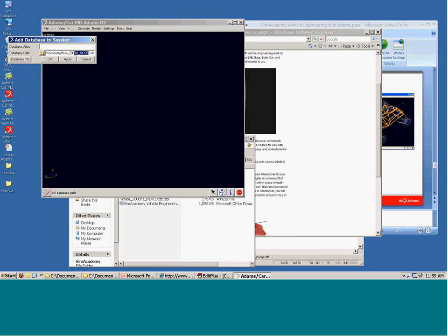Now this is important. The alias is extremely important because that is how files are referenced. We talked about the template subsystem assembly. The way these are linked together is using the alias approach, which database to pick which file from. In this case, the database alias is the same. And generally, it is a good idea to keep your database alias the same as the CDB.